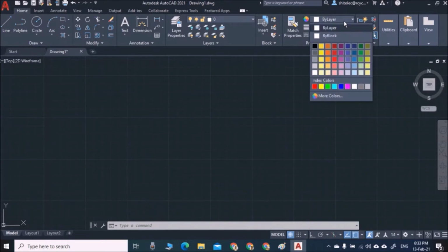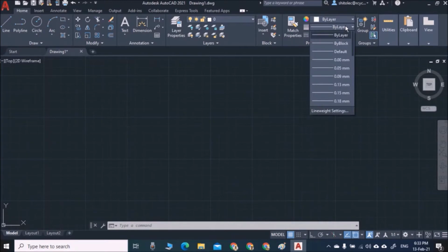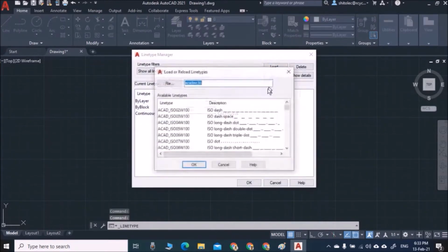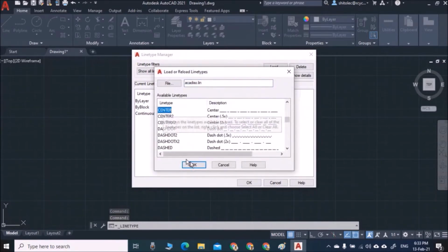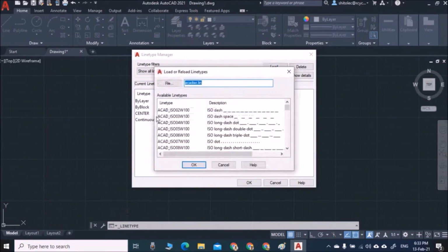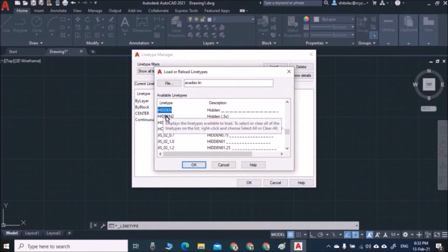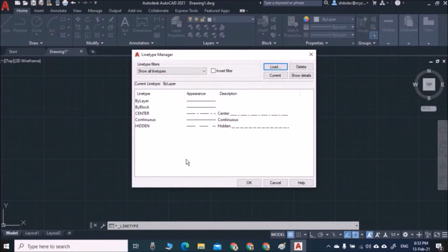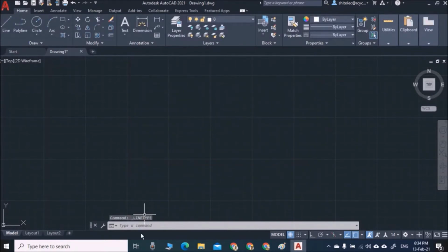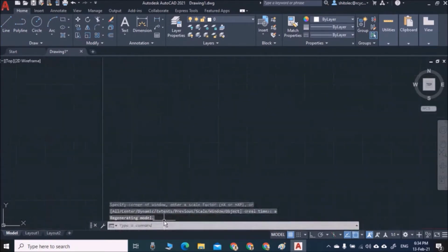Now this is the line color, this is the layer thickness, and this is the line type. So others and load, the center line and hidden line, I need these always, anytime. For hidden line, type H, hit H will get hidden, okay, type C will get center, and okay. And now next is the zoom command, Z enter, A enter always, and dimension style DIM STY.